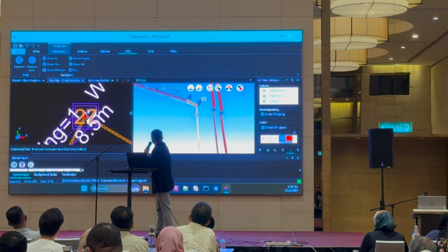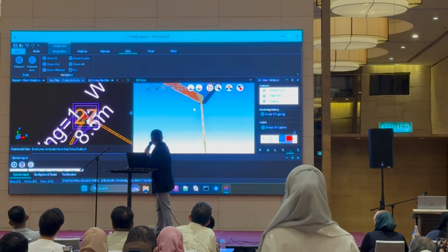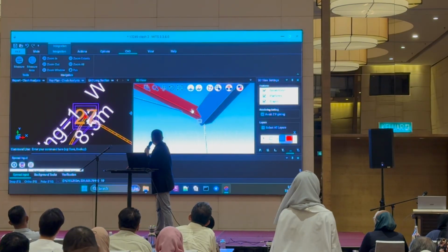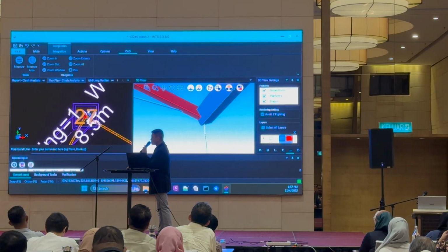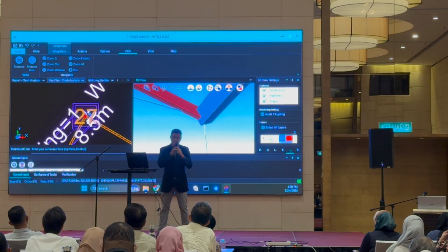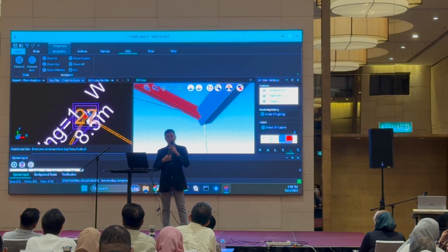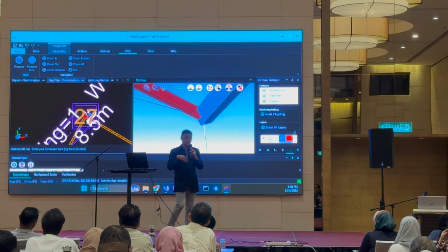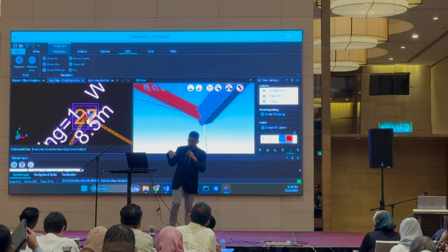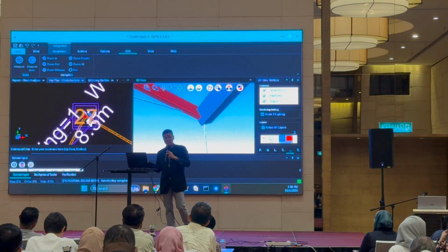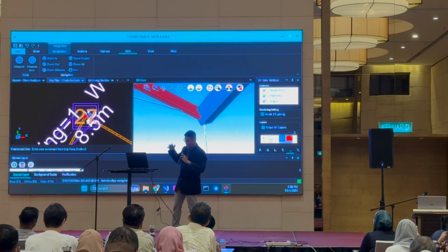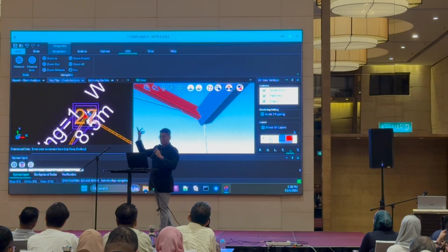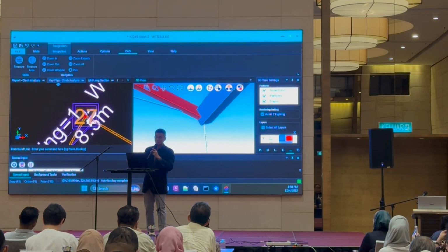See? You can see that the pipes and the drains and this sump, they are all clashing, all right? So this is a feature that is little known, but it's actually very handy, especially when you want to do clash checking, right? Because everything you can do in a single interface, and then you can just click and go to the clash point, and later you can do the resolution if you want to. The 3D view as Amber has shown you this morning.